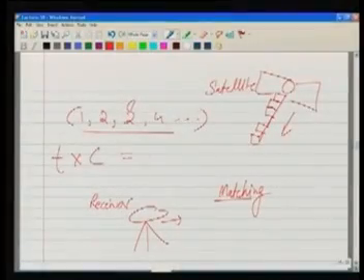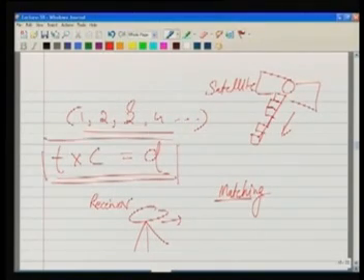If this time of travel is determined, well, it is very easy. We can then multiply it by the velocity of light in order to determine the distance. So this is the clever trick by which the distance from the satellite to the receiver is determined. At the same time, we know the positions of the satellites, and these distances are measured to 3 satellites, 4 satellites, 5 satellites, any number of satellites which are visible to the GPS receiver, and the position where the receiver is can be computed. So this is one way in which we make use of pseudo random code to determine the distance. There are some other ways also.